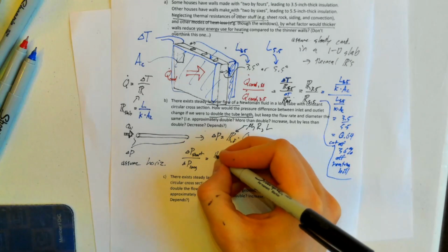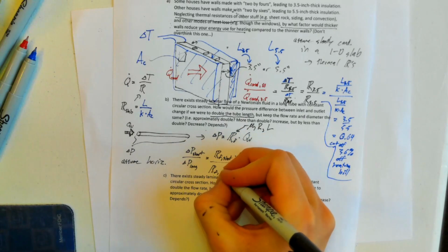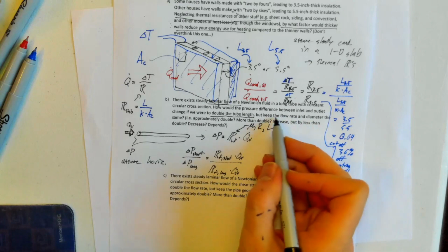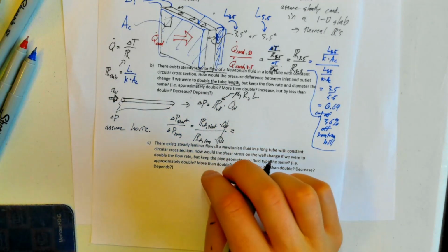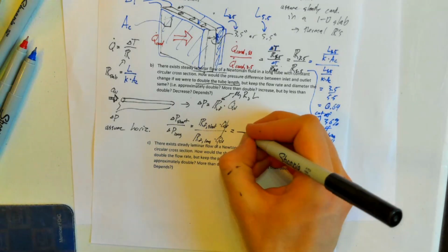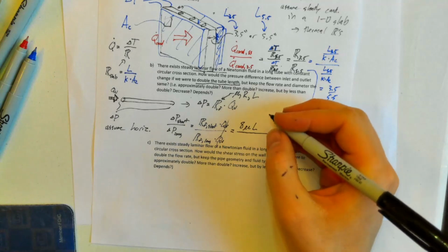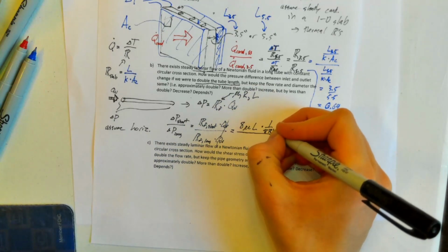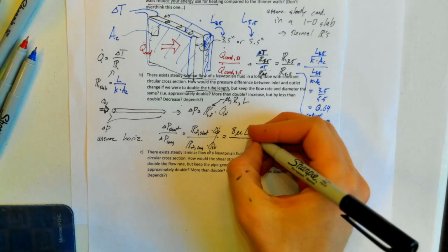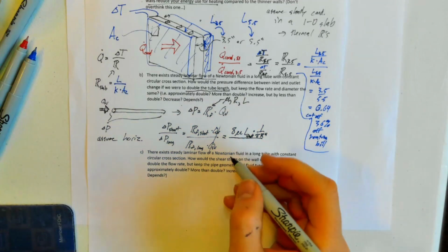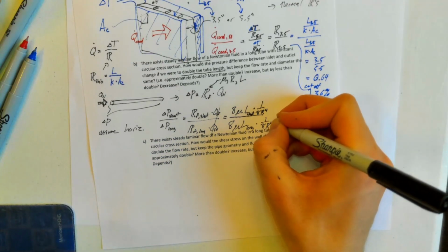And we can essentially say that this is the same as the fluidic resistance for the short tube times the volumetric flow rate divided by the fluidic resistance for the long times its volumetric flow rate. We said that the volumetric flow rate and the tube diameter are the same, so those cancel out. And we can plug in the equation for fluidic resistors. If you do it in terms of radii, the equation is 8 mu L times 1 over pi r to the fourth. And we said we're keeping radius constant, and the same Newtonian fluid, so L, this one would be the length of the short tube. And then we could have the same equation here on the bottom, 8 mu L long times 1 over pi r to the fourth.